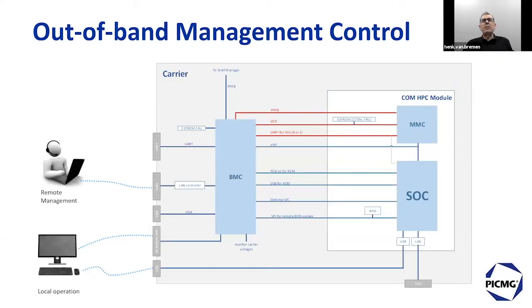One of the last slides, out of band management control. This is typically called IPMI. Many COM-Express form factors have over the years supported something called eAPI, that was specified during the initial COM-Express specification round. eAPI typically focuses on lower level embedded functions that are not abstracted through drivers, such as watchdog, display brightness, backlight control, logistics, and EEPROM storage.